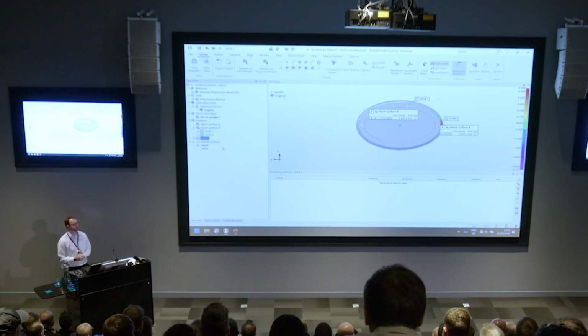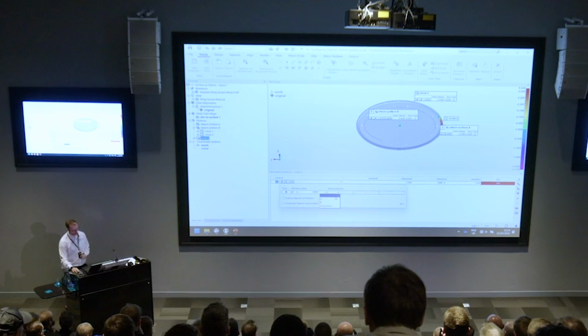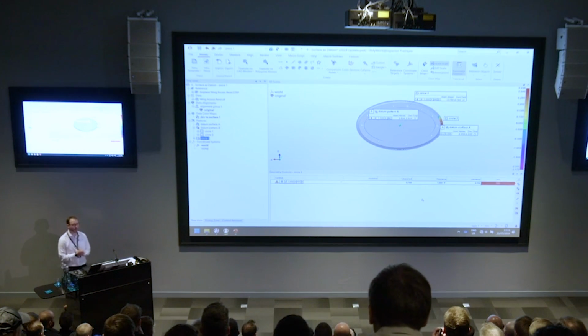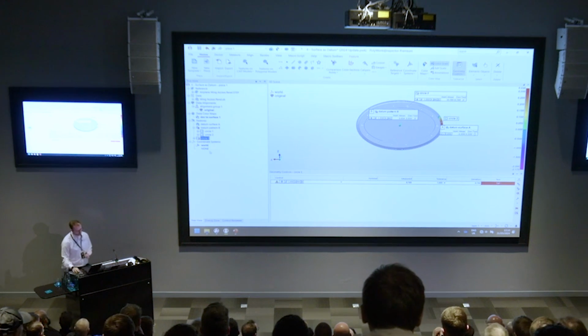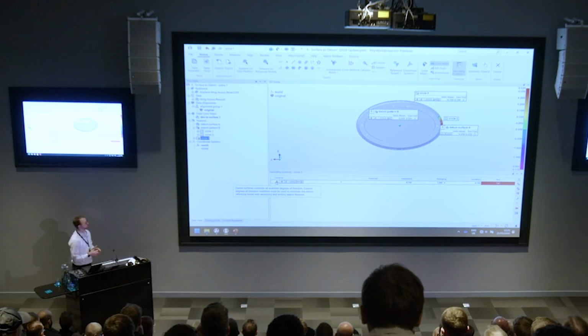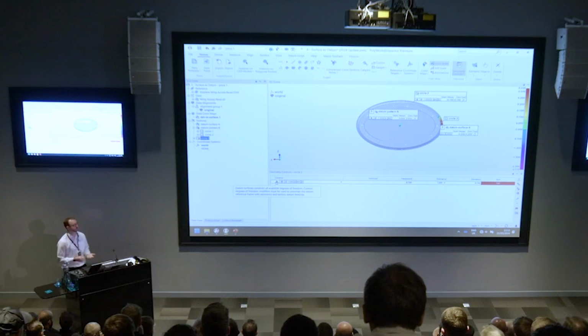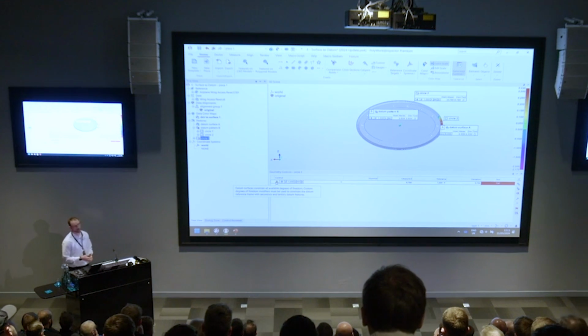To show you the custom degrees of freedom setting, what I'm going to do is circle free at the top here. I'm going to add a position to that. So if I assign that datum A, you'll see this time the BSC modifier is there automatically for us. If I also align it to B as well, so set the DRF to A and B, we don't have an error this time, the yellow triangle indicates a warning. So the way that this works is the A BSC modifier effectively aligns the surface in all 6 degrees of freedom. What the warning is telling me is that as I've included datum B, it's pointless in this case, it's not actually doing anything. So A is controlling all degrees of freedom.